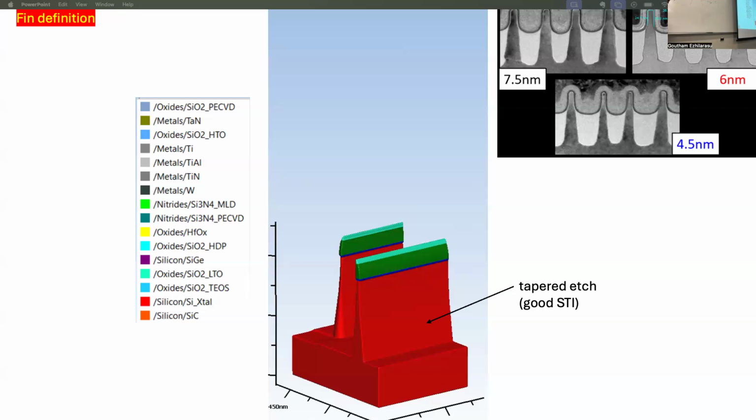So basically you want to create these. Now you have the fin, right? Remember, in the FinFET case, this body is the fin itself. So you need to uniformly dope the fin to the doping of the body. This body is P type here, which means the NMOS fin has to be P-type doped, and the PMOS fin has to be N-type doped, correct? So how do you do that?